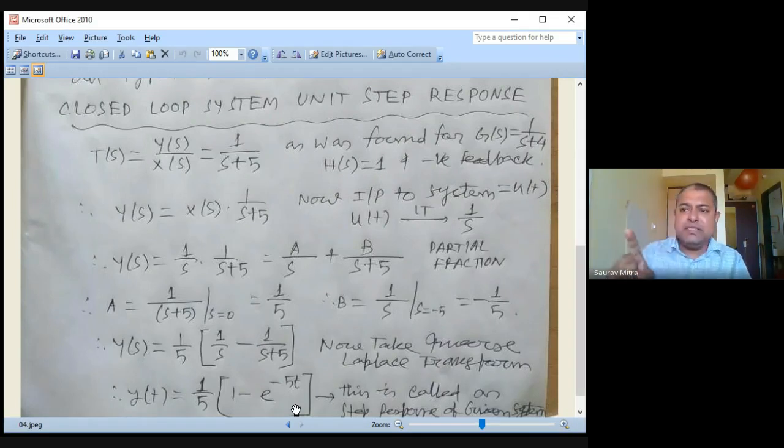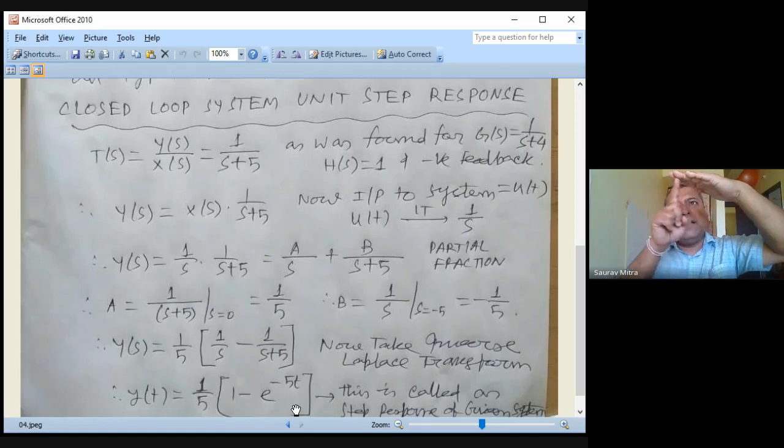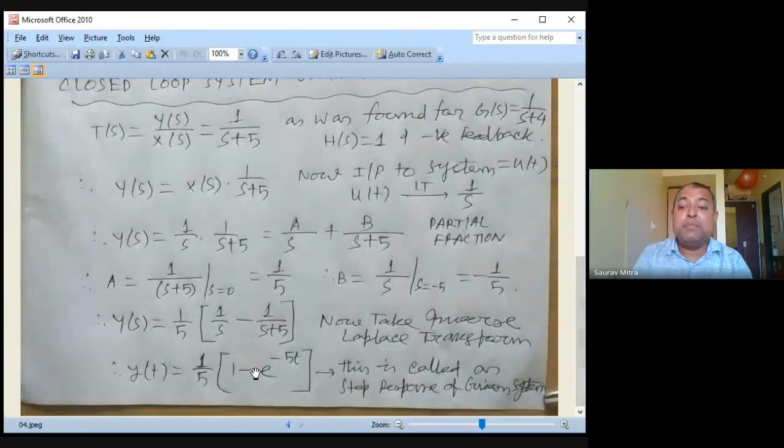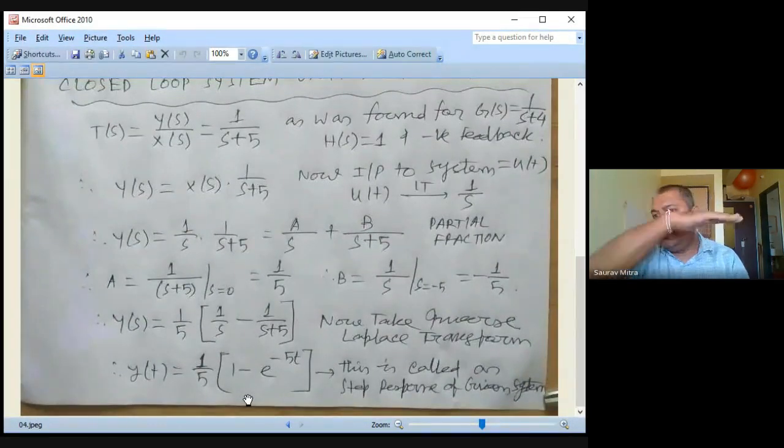This is actually the same as how the capacitor charges. So this is the x-axis, y-axis. This is the unit step input. So it will start like this and it will go and saturate there. So it is an increasing kind of graph. We'll plot it very shortly. This is actually the step response. So don't go on finding stability here, because we are not talking about stability. Stability we talk about in impulse response. Here I have given the step input, that is this unit step input.